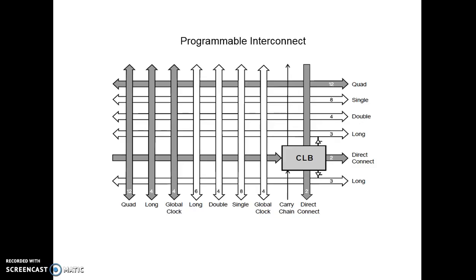The 2 signal groups in direct connect are optimized for flexible connectivity between adjacent blocks without the limitation of small numbers and unidirectional wires. Wires in double groups travel past 2 CLBs before hitting a switch, so they provide shorter delays for longer connections. For really long connections, the long groups don't go through any programmable switches at all.